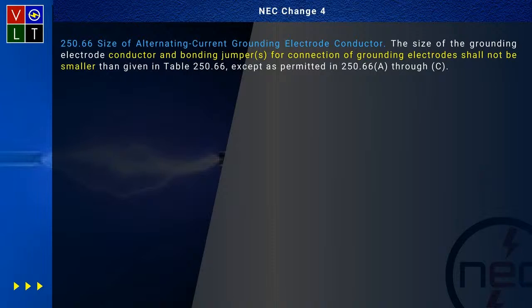Now I want you to look at something. I just brought this up. There was some argument a while back, and they were arguing about one of my questions, and it was about a concrete encased electrode. And I just said, it has to be a 4, period. I'm not going to argue with you. So what they did here, there's some clarification in section 250.66. And I want everybody to listen to what I'm going to say here. The size of the grounding electrode conductor and bonding jumpers for connection of grounding electrodes shall not be smaller than given in where? Table 250.66.